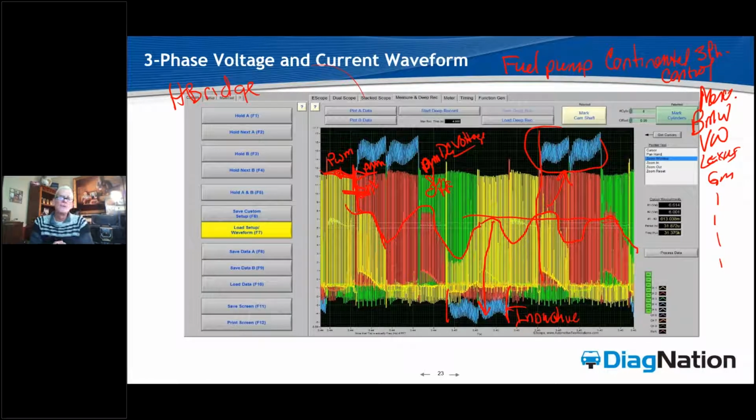And we get AC motor operation out of a DC 12 volt driver. Now, guys, again, there is way too much for me to try to cover here in this class. I wanted to introduce you to this concept, to how it's done, to how it's constructed, to how we look at it on a scope, to the now very common 3-phase voltage controls in cars, and wet your whistle for what will have to become a very steep learning curve for those of us that want to get serious about understanding and diagnosing these systems.